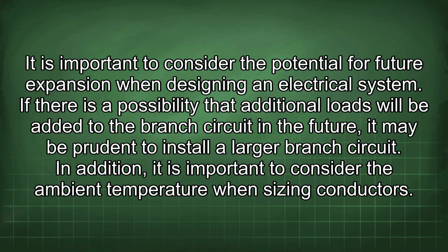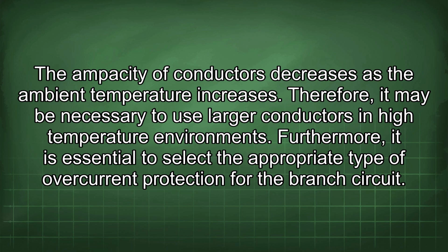In addition, it is important to consider the ambient temperature when sizing conductors. The ampacity of conductors decreases as the ambient temperature increases. Therefore, it may be necessary to use larger conductors in high-temperature environments. Furthermore, it is essential to select the appropriate type of overcurrent protection for the branch circuit.